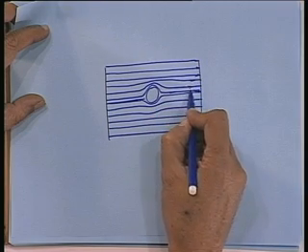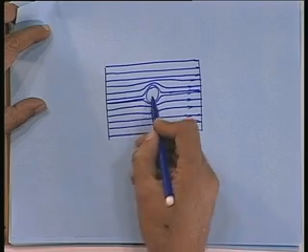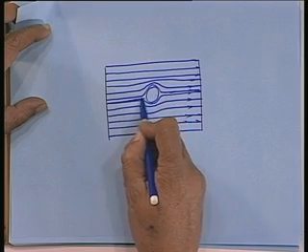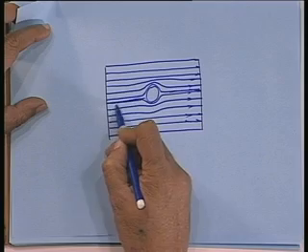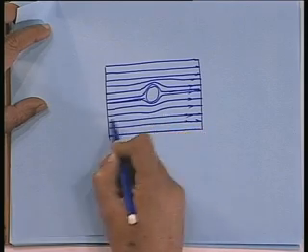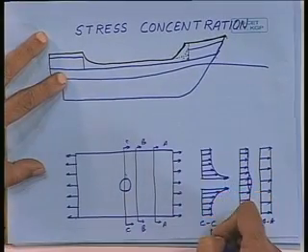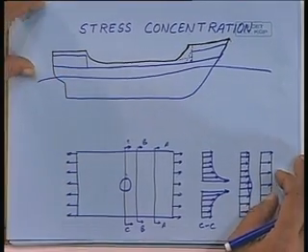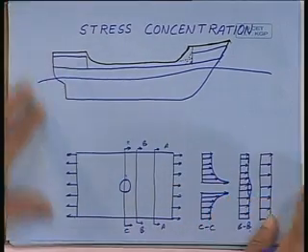Now you see what happens. Because this material is not there, all these stress contours are trying to reach there, but do not find anything. It takes the shortest path and goes like that. As the concentration starts, it gets deflected a little bit, and then it finds that yes, it can go like that. So now if you just try to plot it, that gives you this variation. And you will find that the smaller the hole, the larger this will be.